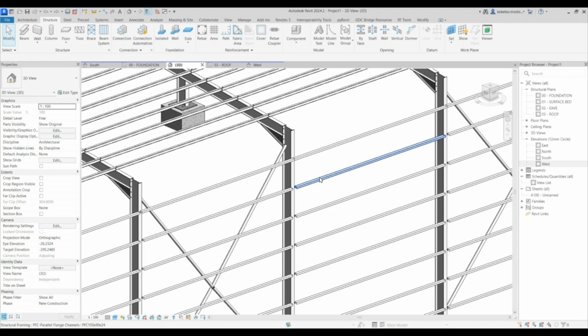So that's basically it. We have connected everything. We have connected our rafters, our purlins, our side rails, our bracings, our columns, and so on. We have our base plates. And this is it. This is a level of detail 500 structural warehouse or portal frame. Obviously, you can apply rebar towards these bases if you want, but this is essentially it. Very much valuable if you're under subcontractors or if you're under a manufacturing company. Produce one of these. So yeah, thank you guys for watching, and I'll see you on the next tutorial.